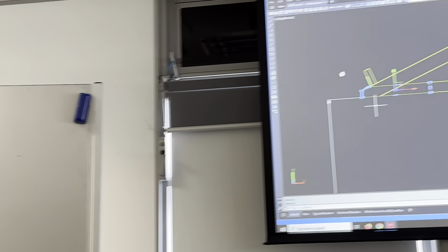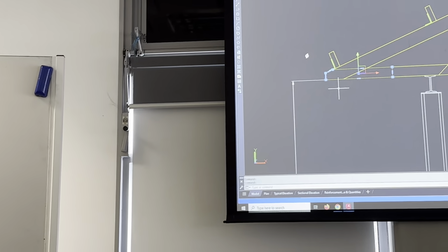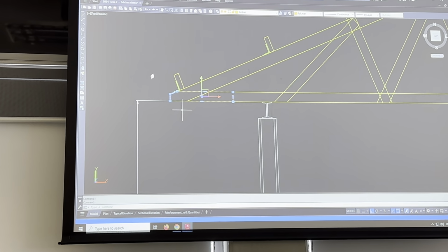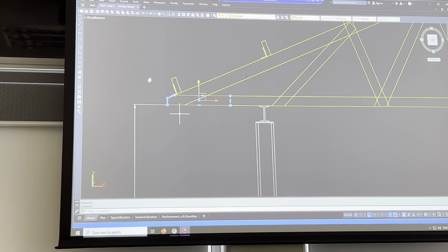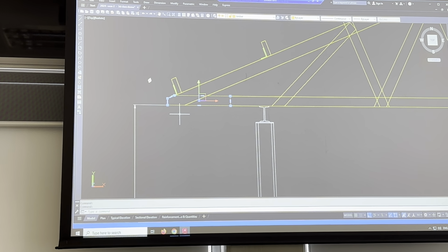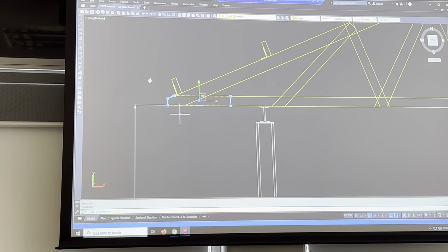So a lot of trusses have got these split rings on them because you don't want it moving like that, and you don't want it moving like that, and you don't want it moving sideways too. So what that does, the claw, the picture is in my timber notes where you'll see it in the timber, pulls it all together, and there's quite a few of those on this truss.